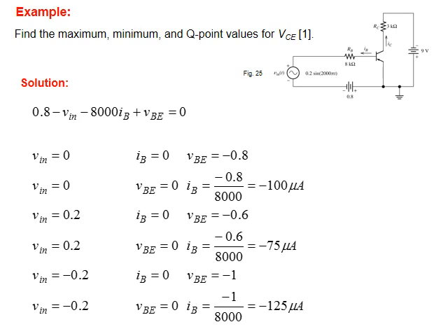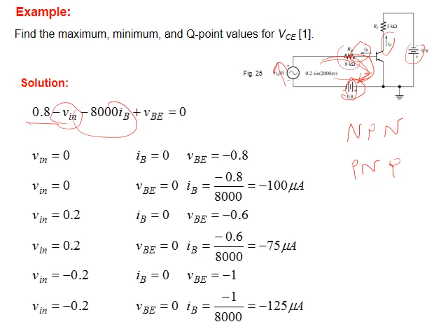Now just a quick mention. You may ask, till now we are discussing the NPN transistor. What about PNP? PNP, the same procedure, but the only difference is the directions of current, as you can see here, is the opposite direction. Voltages are in the opposite direction. So when we write the formula here, as an example for this situation, VBB, this voltage, Kirchhoff in this direction, minus Vn because it's in the opposite direction, minus the drop across this resistance, plus the voltage here because it is in the right direction. So this is the formula.